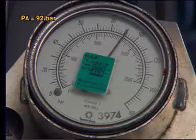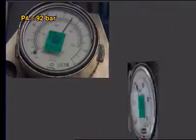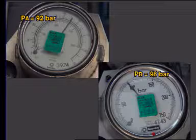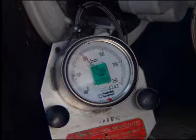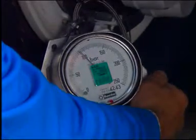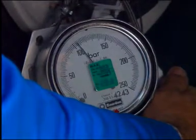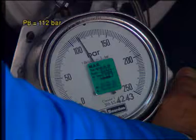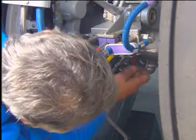Read and record the pressure shown on the pressure gauge, and then close it. As the pressure condition is not fulfilled, we have to increase the pressure in the bottom chamber by adding nitrogen. On the bottom charging valve, the bottom charging valve being open, open the control supply valve slowly to add nitrogen to the bottom chamber. And close the bottom charging valve.